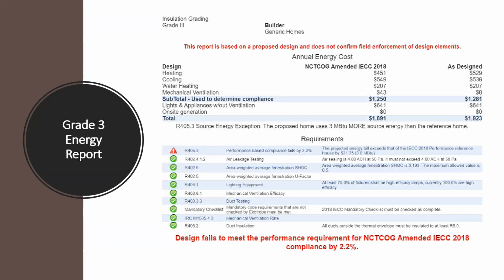So it's not just the dollar amount that changes. What also changes is CO2 gas emissions, natural gas consumption, and of course the total electrical consumption of the whole building. Lastly, if the builder is also following an ERI path, the score did change from grade 1, 2, and 3 by 1 point. Not a lot, but it did change by 1 point. So if you're following the ERI path and you need to hit 56 and it moved to 57, then you failed energy modeling, and the models actually failed. Permit documentation should not be approved. It should go back and be readjusted.